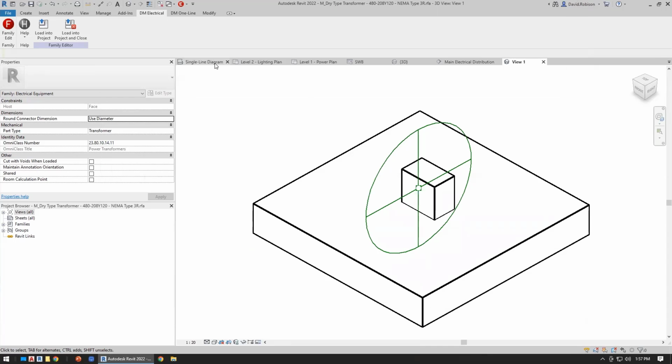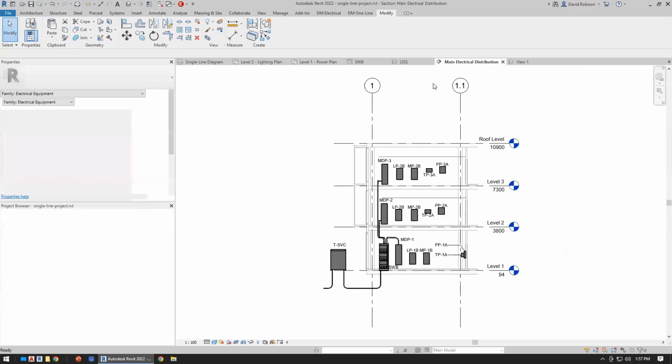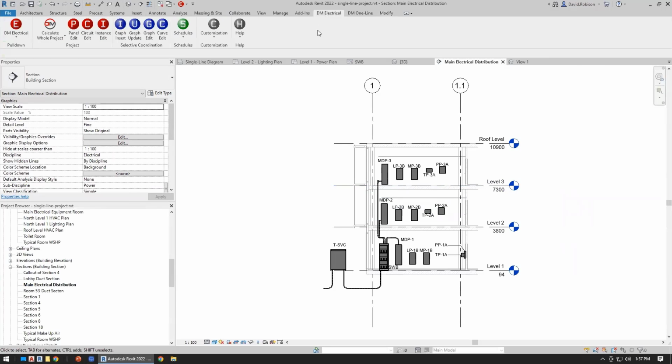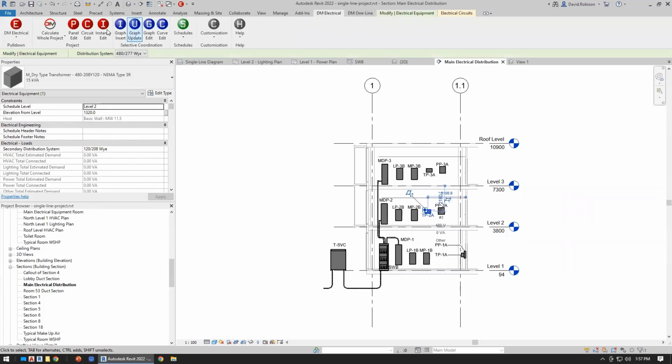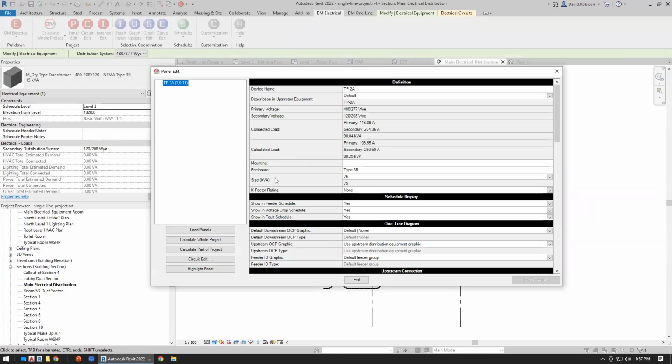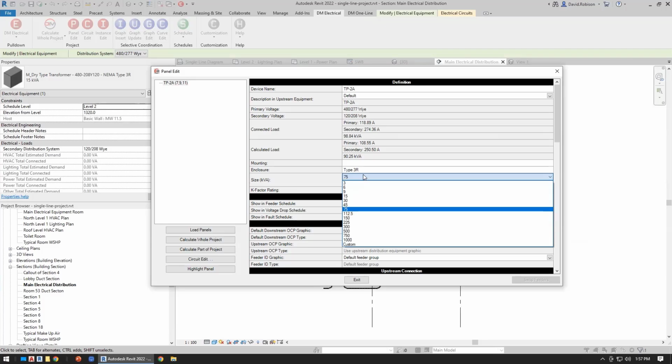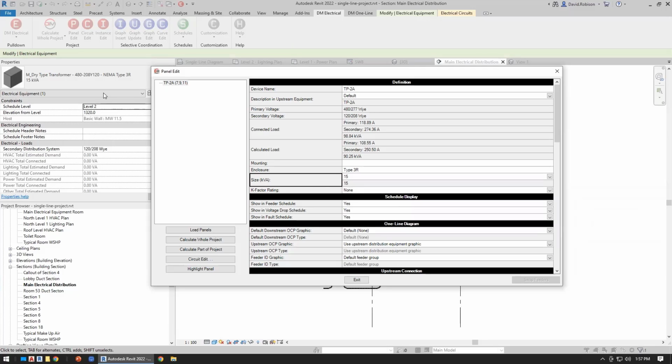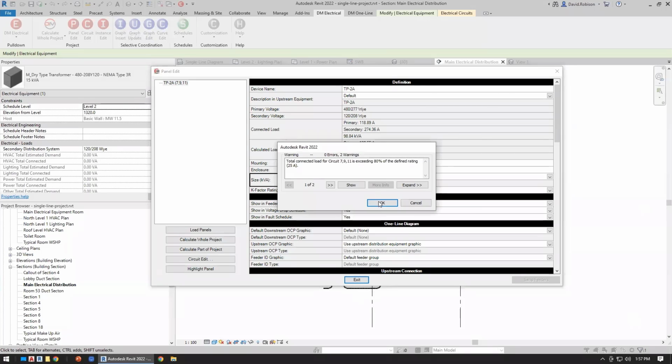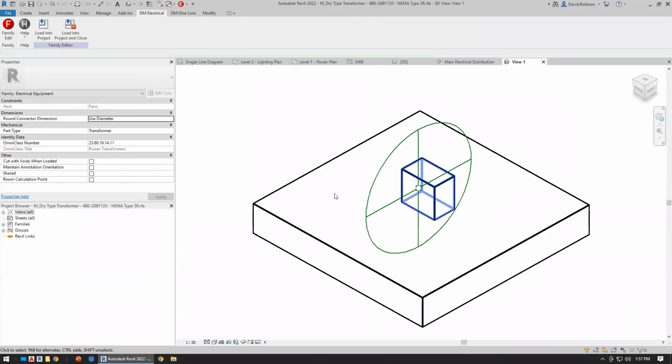So click OK. I'm going to go over to the project real quick before loading it. So I haven't loaded those changes yet. If we select this panel and we run the panel edit, really the transformer, you can see that we have the kVA here and we can actually change it. So we can specify what this kVA is. It's not telling us because it doesn't know, because Revit doesn't have that as an intrinsic property. So we can specify it as a 15 kVA transformer to match that type. So that's kind of out of the box how it works with families if you don't use the family edit command. So now, using the family edit command and loading these changes that we've made into my project.